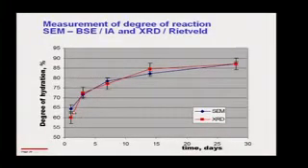We can still deal with that if we use a standard, if we always compare our spectrum from our sample with a spectrum from a standard, for example, corundum, then we can back calculate the amount of amorphous material. This is all now quite well-established technology, and this gives an example here of how we can measure the degree of hydration either by X-ray diffraction Rietveld method or by scanning electron microscopy, as I'm going to show you in a short while, and both give very comparable answers, and you can see the intrinsic errors in this system.